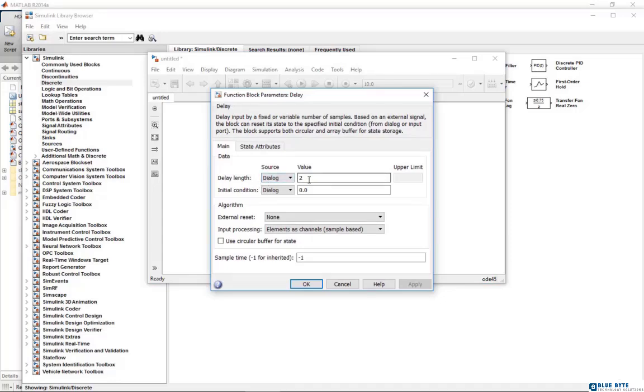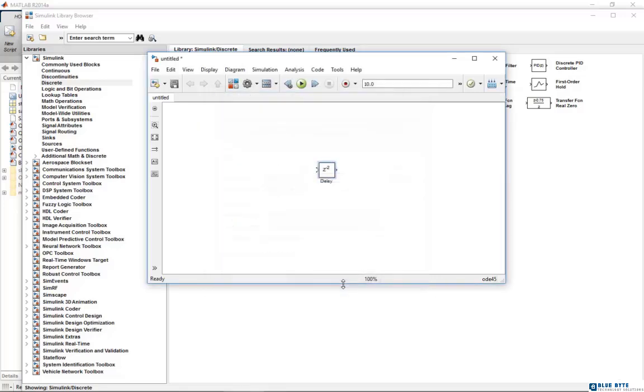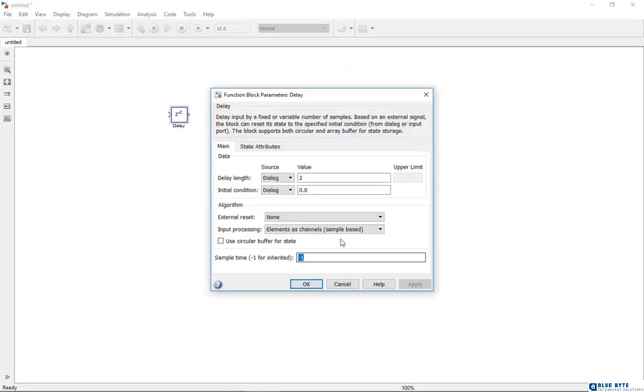The point in simulation of a discrete system is sample time. Here, sample time specifies the steps in the simulation. Now, if I enter 0.1, MATLAB performs the process of solving discrete equations based on this amount. For example, if I set the delay length to 5, it means that the system has 5 units of delay from that 0.1. I will talk about it more later.